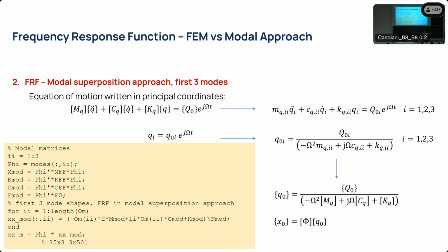We can compute the frequency response functions, we can integrate them, we can do whatever MATLAB allows you to do with them, and we end up obtaining a vector of modal coordinates, which can be complex if we want to compute the frequency response function, or a vector of modal coordinates with respect to time if we want to integrate that equation with ODE45 to find the time response of your structure, because that is also something you can do with finite element analysis.